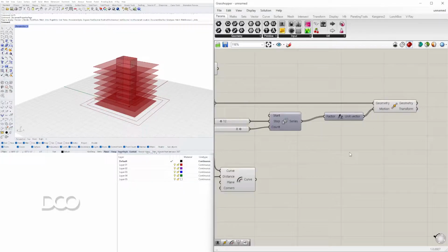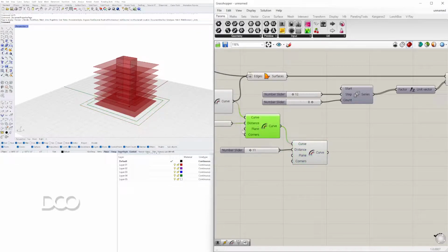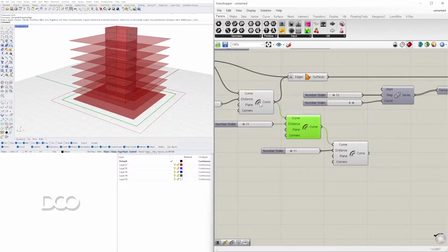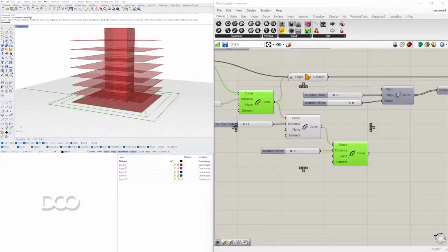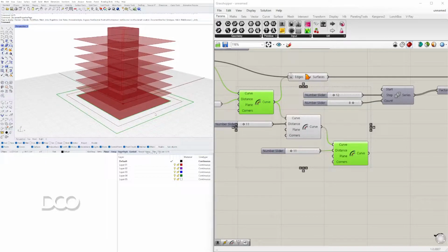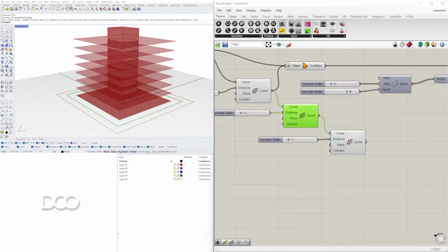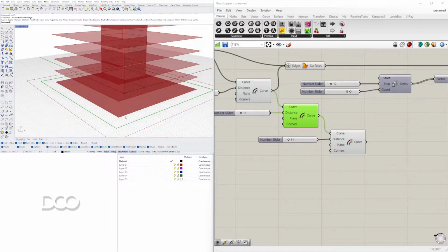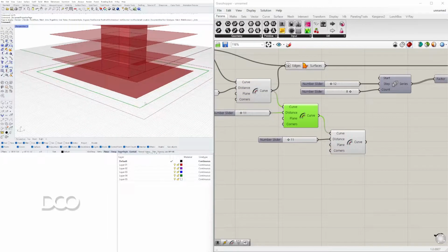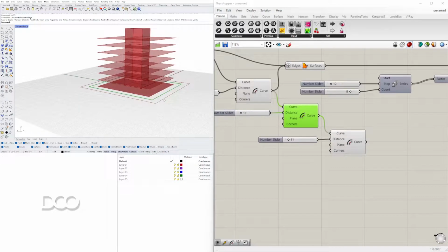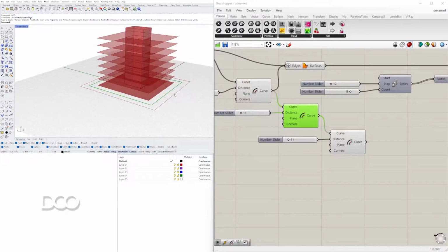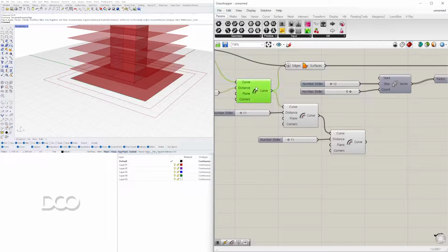All right, so at this point, we're going to take these lines, so between this one and this one out here, and that's what we're going to be using to create the ramp. Now, the reason why we have this line here is because technically we only have a minimum distance for a ramp, and this leftover portion is actually going to be for subtracting the ramp, and you'll see that in a second. So let's create the ramp between this line and this offset.